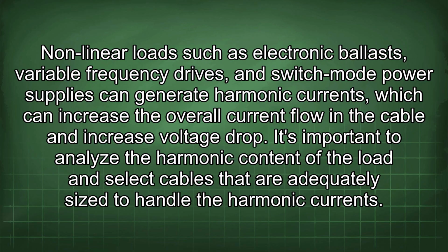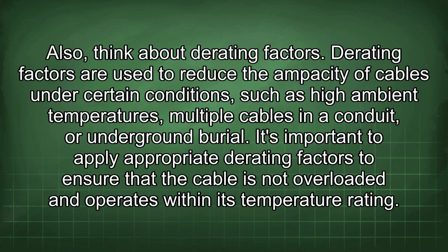Nonlinear loads such as electronic ballasts, variable frequency drives, and switch mode power supplies can generate harmonic currents, which can increase the overall current flow in the cable and increase voltage drop. It's important to analyze the harmonic content of the load and select cables that are adequately sized to handle the harmonic currents. Also, think about derating factors.